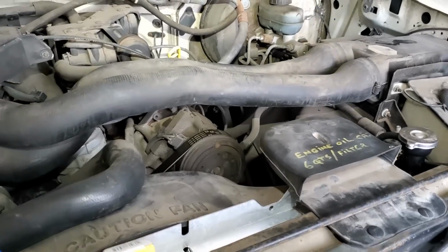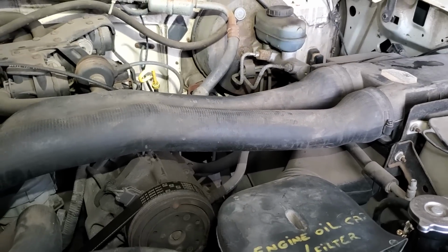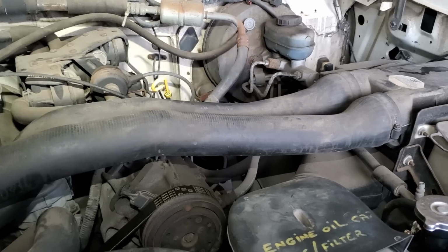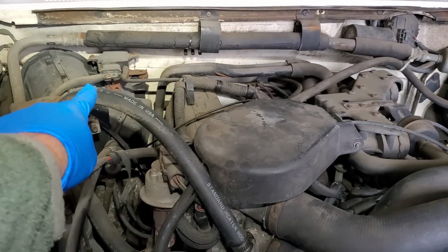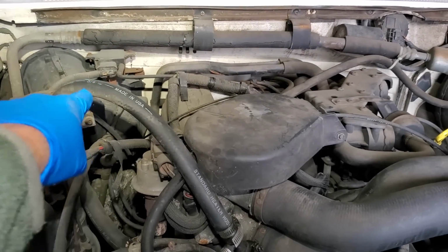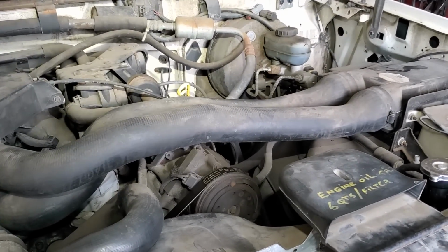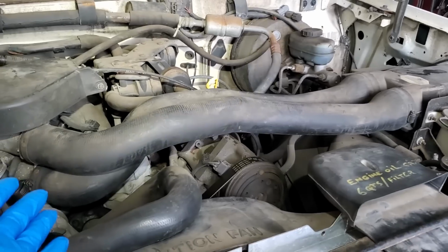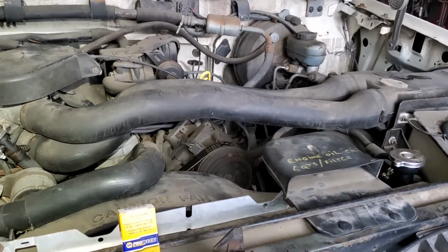The other thing was a lot about the learned memory. And these are not like modern vehicles with complex fuel trims and mapping and all that. They're very basic. It's a very basic speed density system. It uses a map sensor. These do not use a mass airflow. And although there might be some keep alive memory, it's very limited compared to what we deal with now. This is like, what, Windows 3.1?